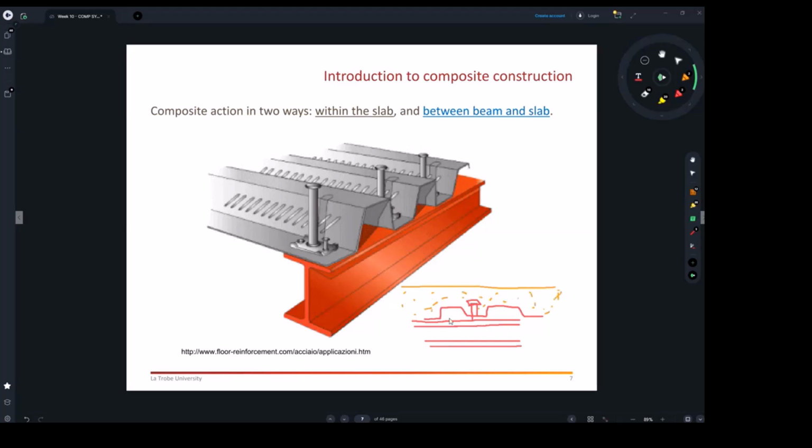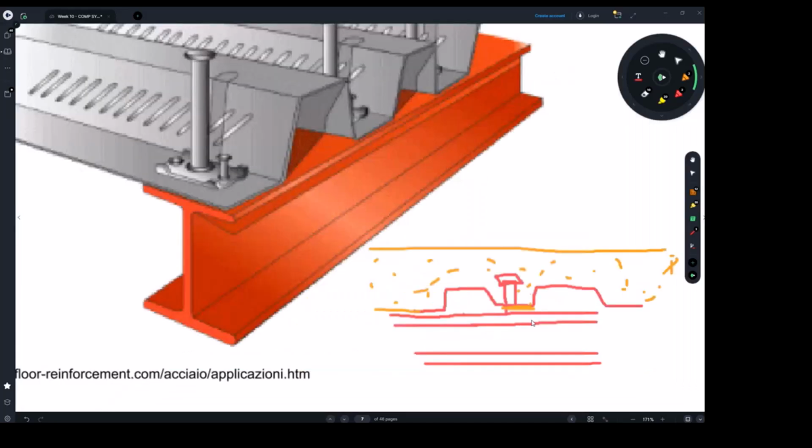And in this case, the steel beam is going to act with the slab to resist whatever load it's actually resisting, because mechanically we have managed to do this, right? And the designer will be taking into account, remember, there is no gap at this point, because that's where the deck is sitting. But here there's going to be a gap, and that will be considered by the designer.